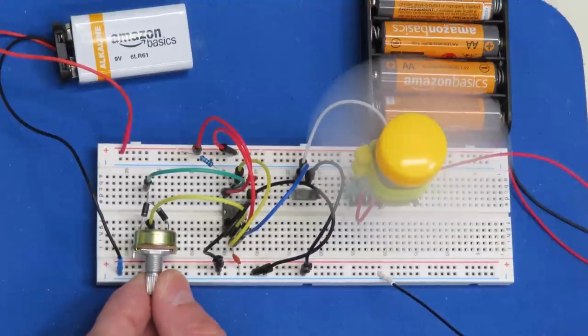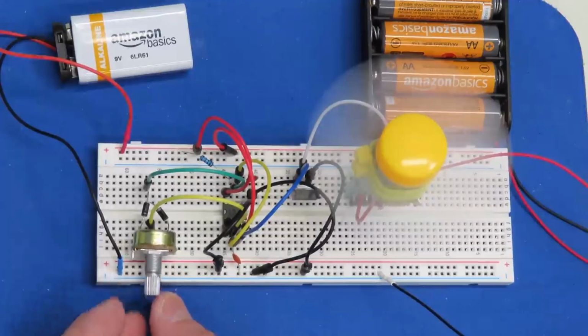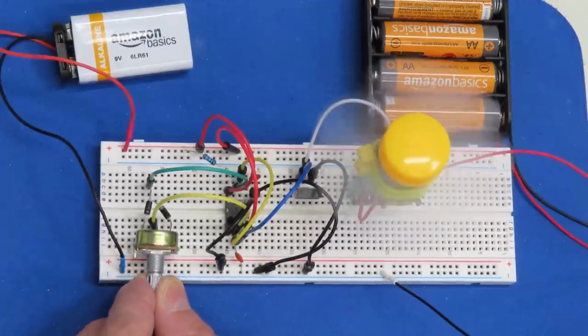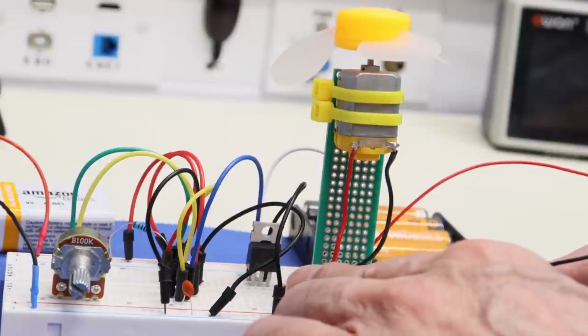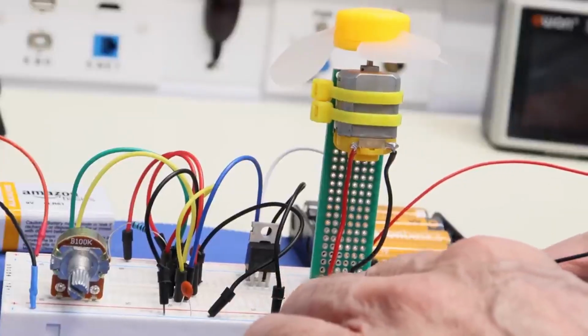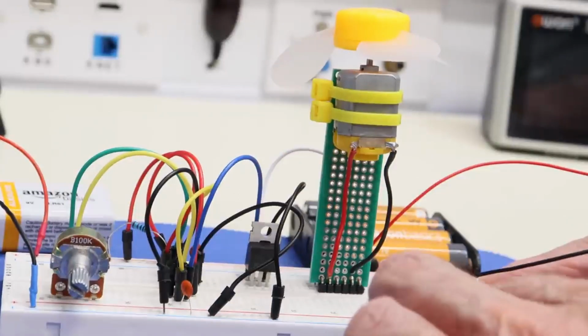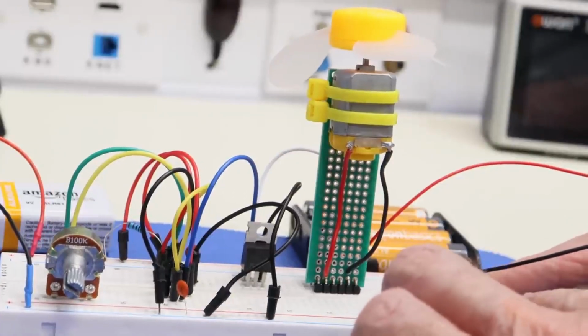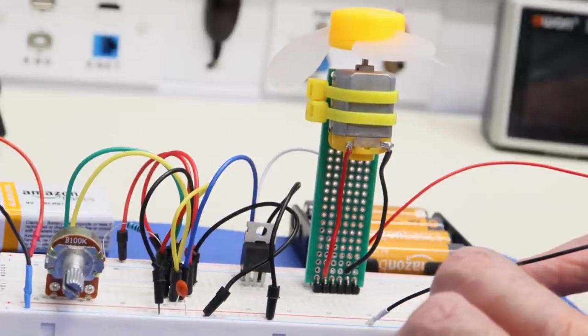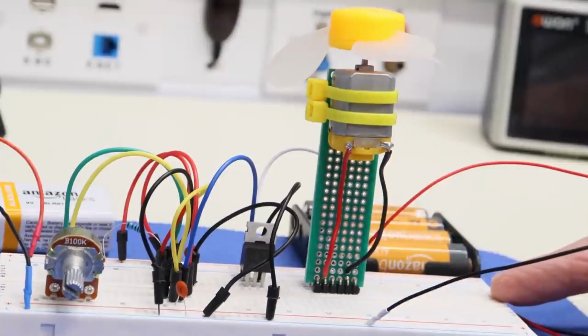But once again, I want you to bear in mind the cost of the devices over here. We're using essentially the same MOSFET that we would use with an Arduino based design, but we're using a very inexpensive 555 timer chip. And so this is a much cheaper design than an Arduino based design, and if all you want to do is control the speed of a DC motor, this will work great.